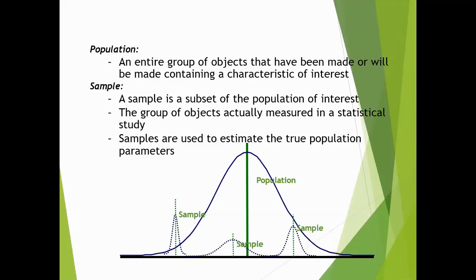Now, when we did the process capability, we have seen something. We definitely map the process in a distribution curve, and we also had two things, right? One is lower specification limit and upper specification limit. That was given by the customer. In statistical process control, what we do is we feed in the data, a sample data that we collect for this particular activity. And there is something called a control limit. So you'll have a lower control limit and upper control limit. And that is not assigned by the customer. That is calculated by statistics, right?